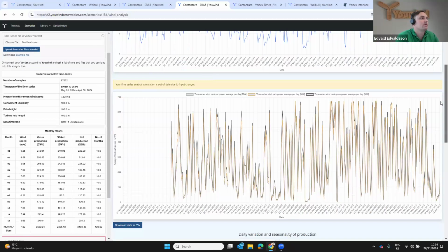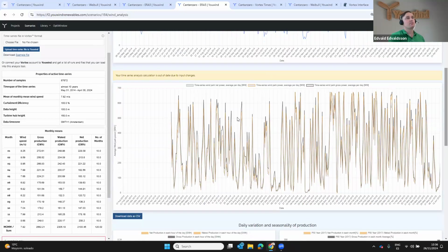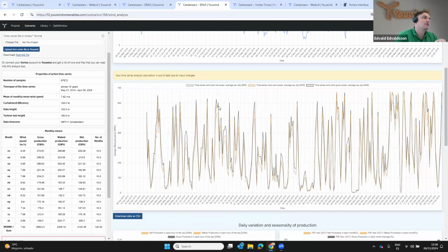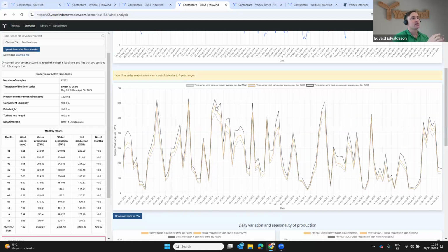You can also add here, and this is something that we use quite frequently, something that we've worked quite hard on evaluating: if there is a possibility for curtailment, or if the developer wants to evaluate what sort of overplanting or underplanting scenarios they want to see, then it's possible to go into very fine detail. If there's a risk of curtailments or a maximum cap on export capacity, it's also possible to go even down to 10-minute averages using the time series product and evaluate what the impact would be on the overall efficiency of the layout. This all applies whether you would have 1 offshore substation or 2 or even 3, and the type of export cable capacity you might have.